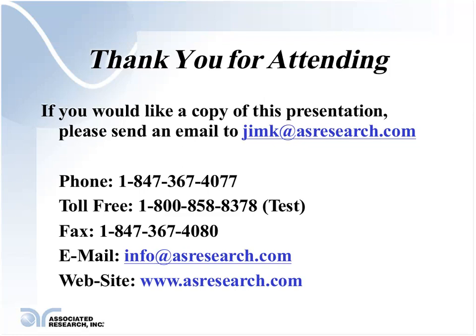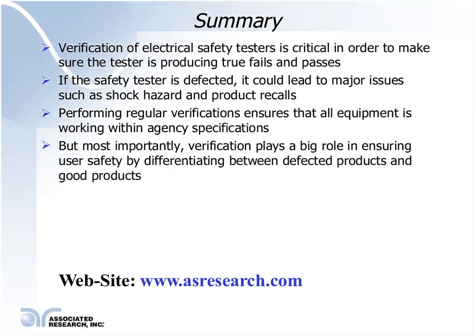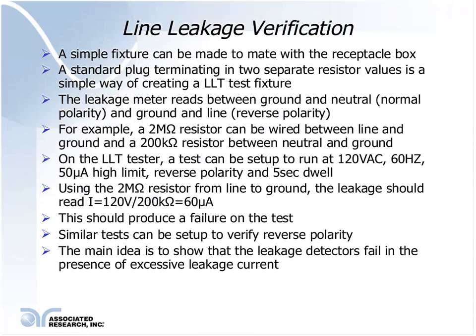Okay, one quick comment on one of your last slides. I think you had a typo on one of your resistance values on the line leakage test, 120 volt with 200k. It should have been 600 microamps rather than 60.